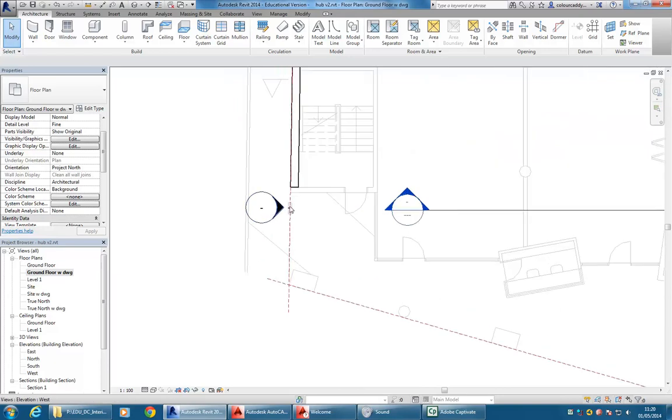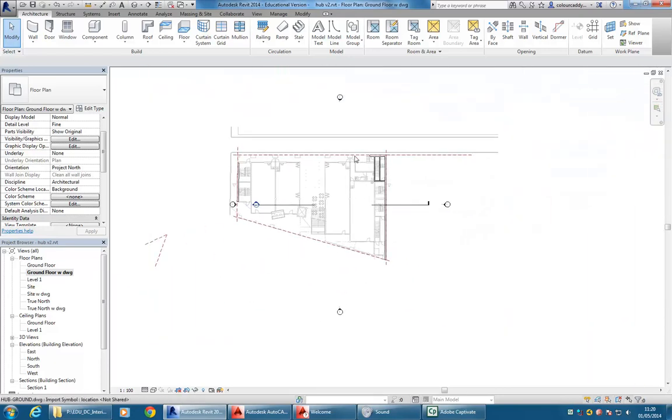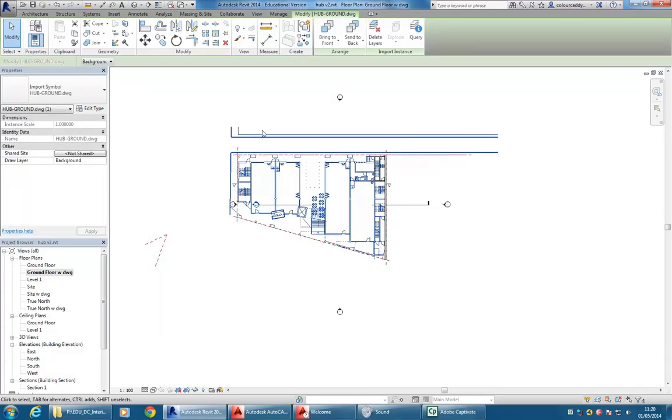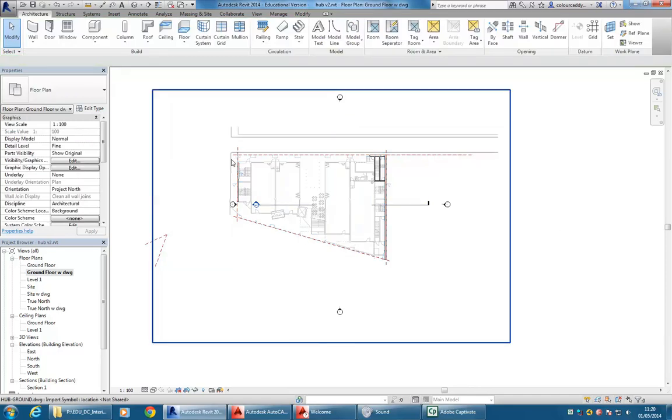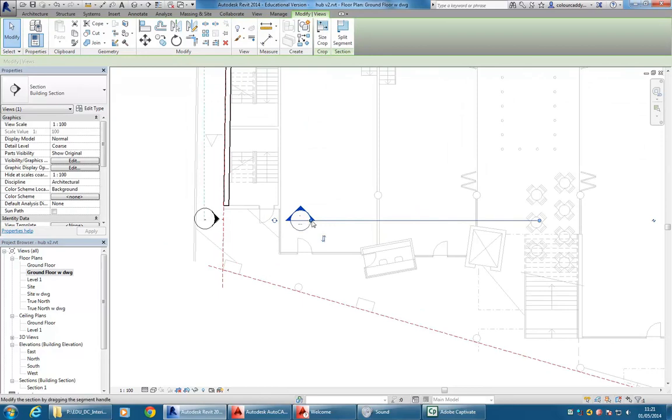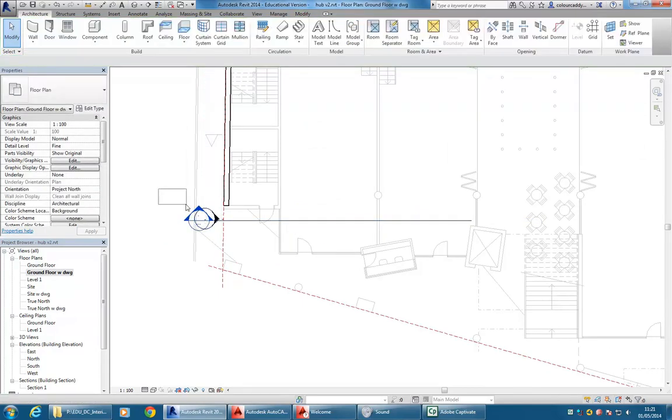With the views, you can see there, I've actually left the views the way they are when you first start. So the elevations are in that sort of cross pattern. But I've at least tried to get the AutoCAD lines and everything else centered roughly within those. But then you can see if I grab the section line, I can now bring that out so that it's the size I want. I'll get that elevation as well.